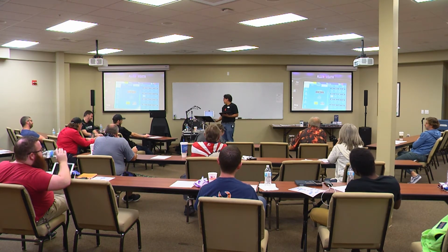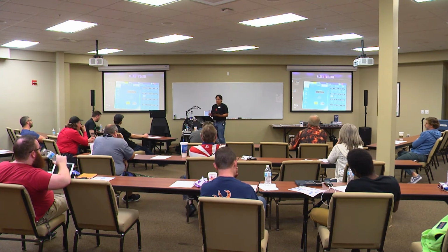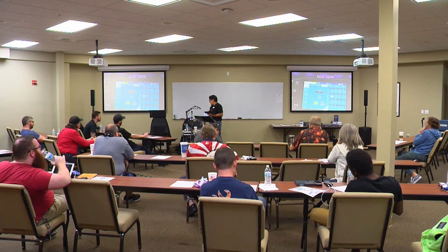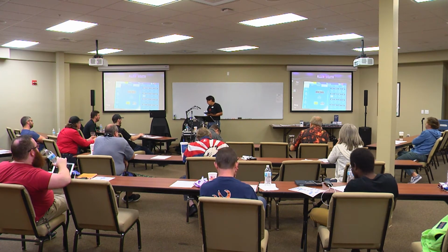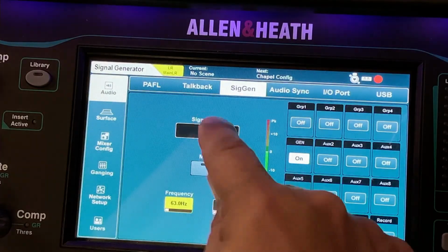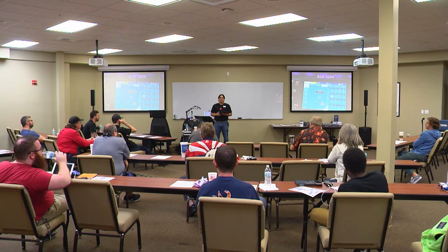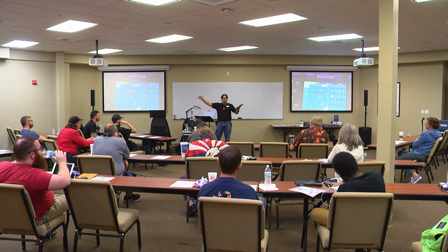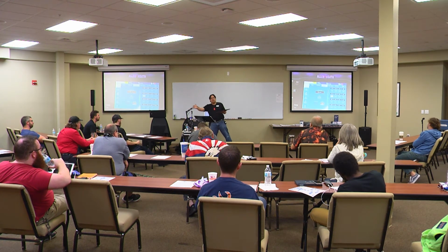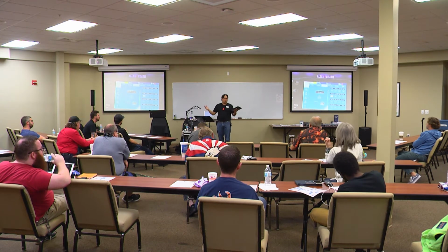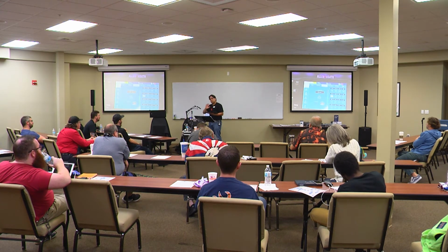All right, so polarity. Now we're going to filters. If you watch the video, we're talking about high and low pass filters. And let me throw this back on. Pink noise. When you hear pink noise, just for reference, it's randomized noise at all frequencies, 20 hertz to 20,000 hertz, and we use that as a measurement noise, basically. A lot of times it's just like, is it on? Oh, I hear pink, okay, we're good. We actually use that in measurements, and we won't discuss that too much, but we'll show you some things later on.